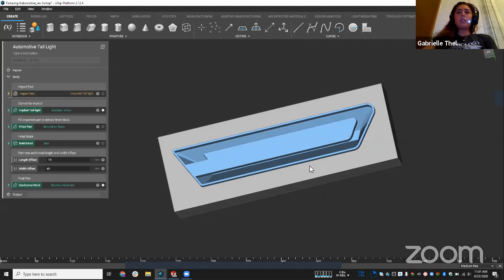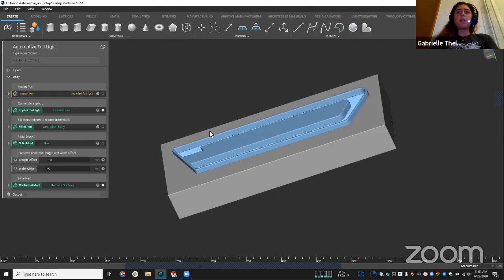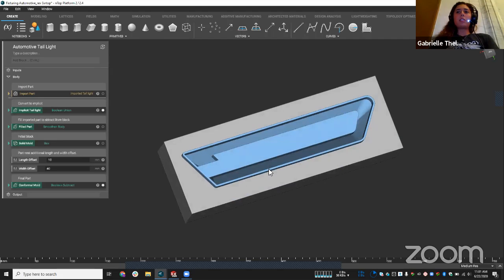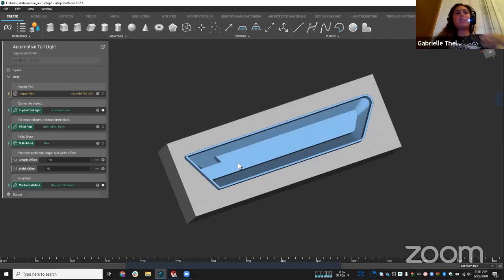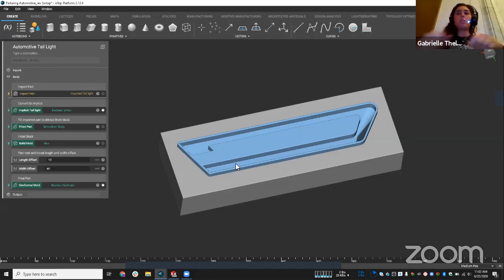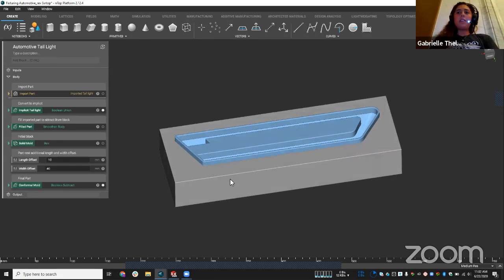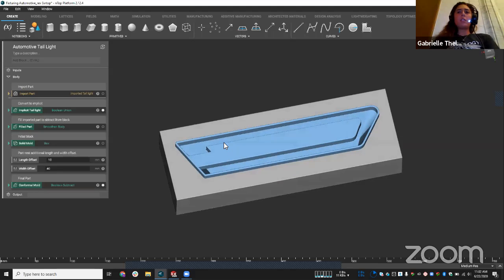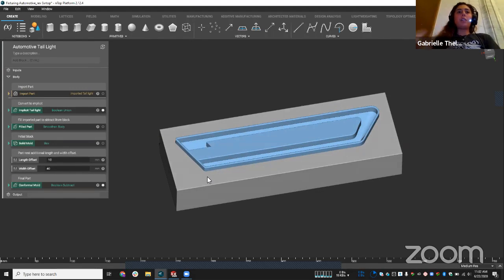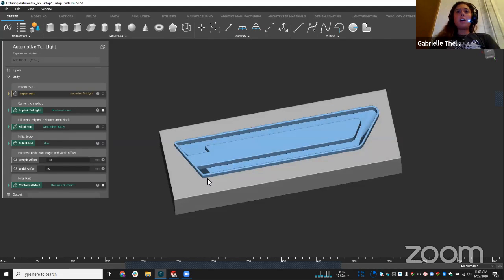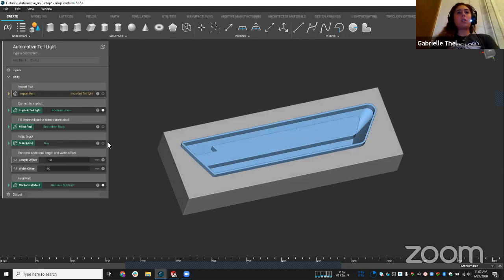So the assembly and testing of these taillights involves welding tabs, driving screws, testing lighting connections, etc. In many cases, it involves an operator loading the parts into a part nest, and then the assembly and testing operations are automated, whether it be through robots coming in, welding these tabs, or other actuators performing these operations. All in all, it's really important that these taillights remain securely in place during these operations, and that the outer surfaces don't get damaged or scratched.